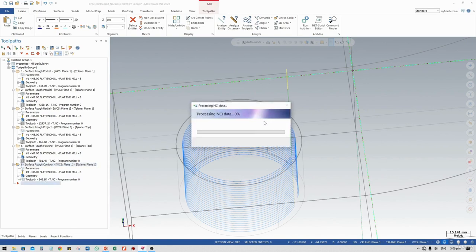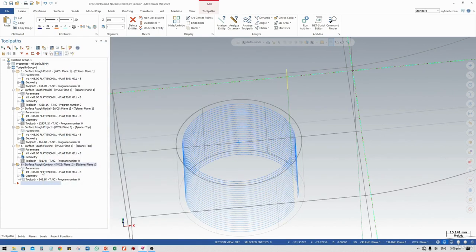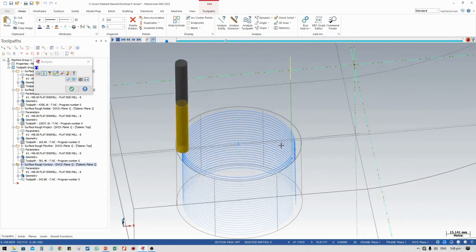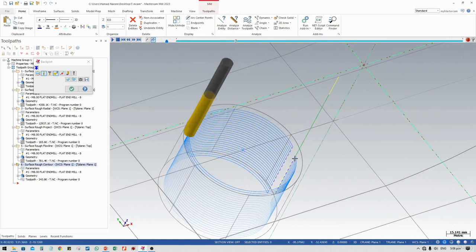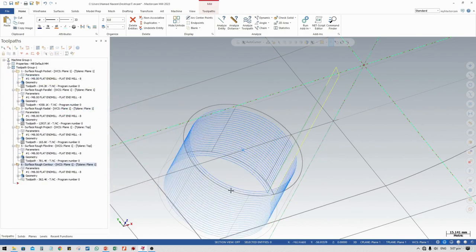So it's just processing the data, the clean movement, showing like this. So this is how it works. We have already selected the direction of cut. It's 2-way or 3-way, so therefore it's done like this, okay? Or you can change the parameters, ramp way in a 2-way or 1-way direction, okay? Or we can say follow the surface, 1-way. Click OK. Just make it 1-way.